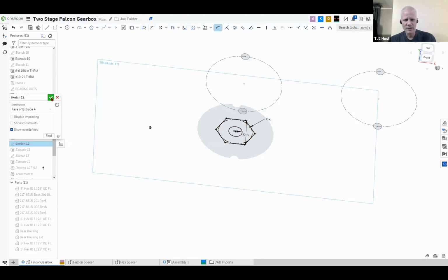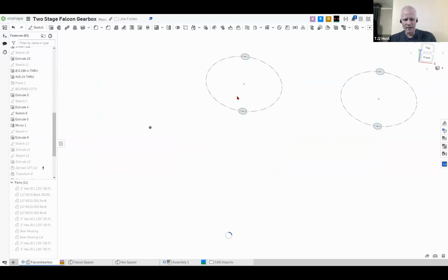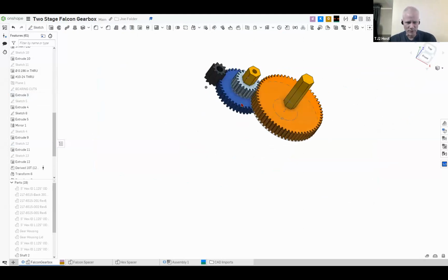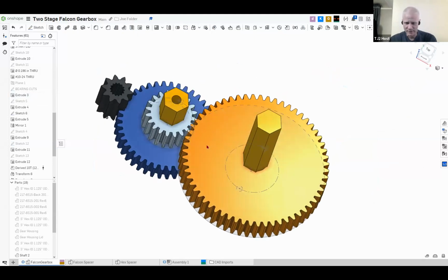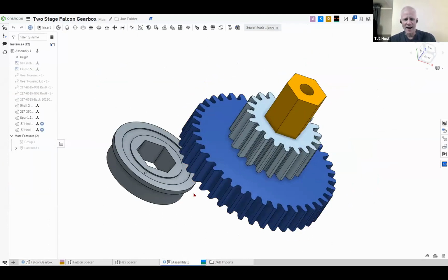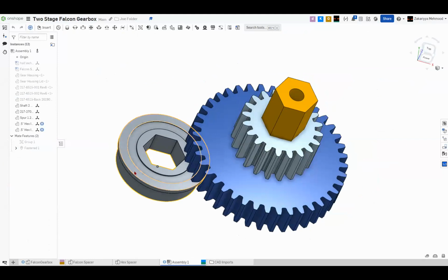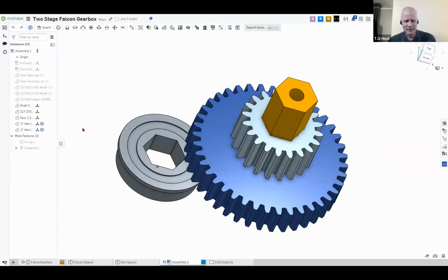Okay, so now if we hit exit the sketch, now everything will be fine. All right, now we've got the hole in that place and the next person will put a hole in there when they're going to do this thing. So now go back to the full assembly. And now we can mate, we can fasten, right? So let's fasten one of the bearings to this thing.